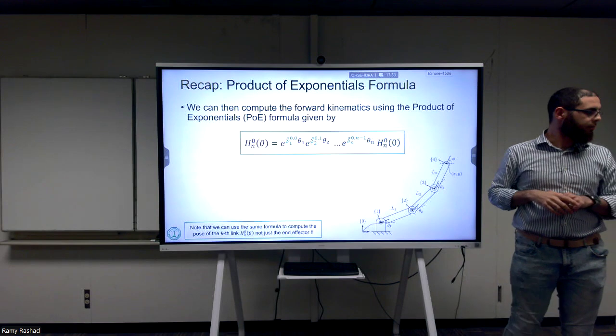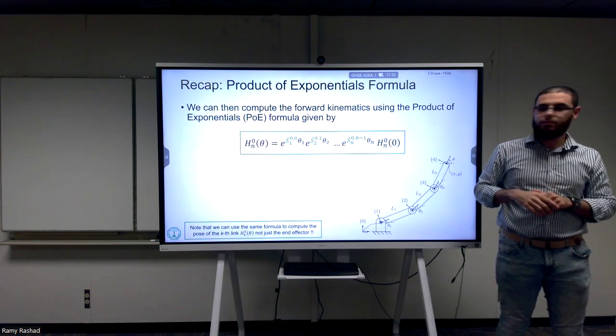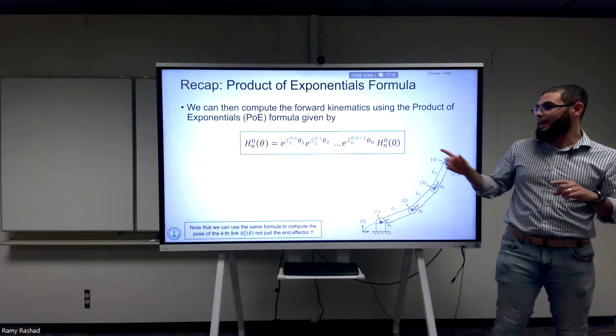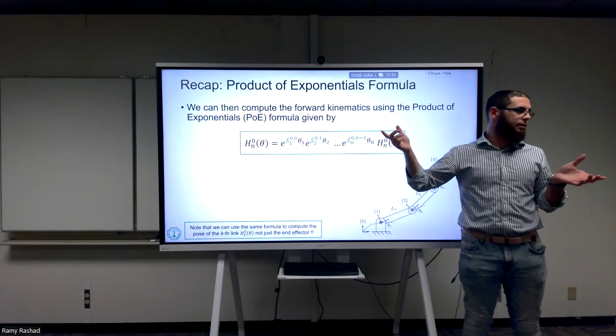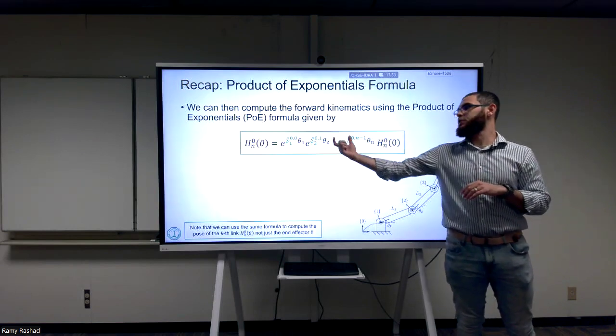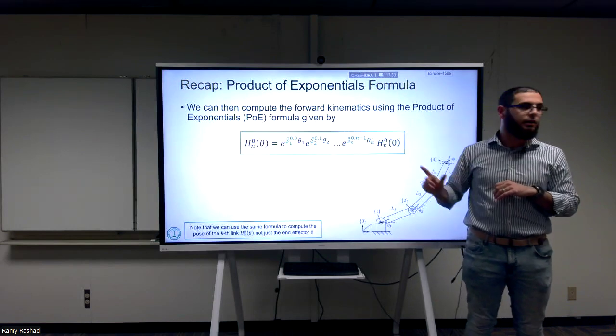Yeah. Because we want to use the Rodriguez formula, that's why we're not combining the exponentials. Because, as with indices, you can add the powers. No, you cannot do that. And you asked this last time. You cannot add, because this is not a nice scalar exponential. This is just homogeneous transformation multiplied by homogeneous transformation multiplied by homogeneous transformation. You cannot add here the exponentials.